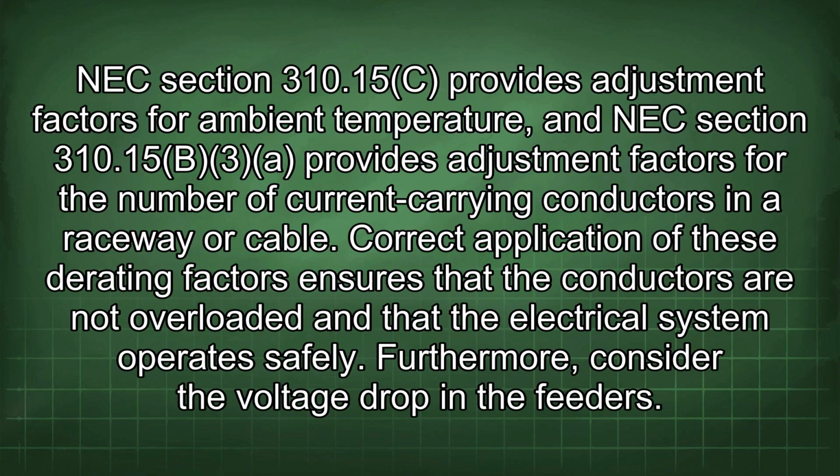NEC Section 310.15(C) provides adjustment factors for ambient temperature, and NEC Section 310.15(B)(3) provides adjustment factors for the number of current-carrying conductors in a raceway or cable. Correct application of these derating factors ensures that the conductors are not overloaded and that the electrical system operates safely.